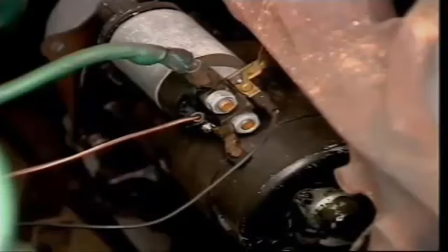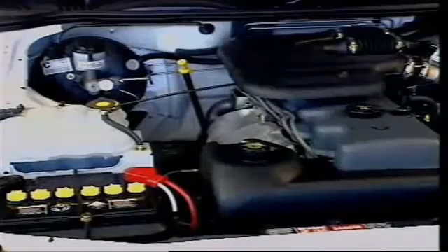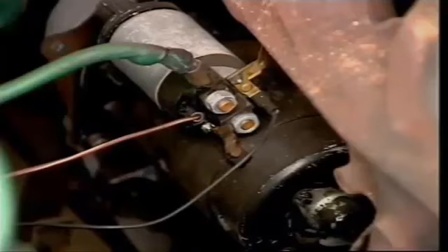The starter motor is an electric motor mounted on the engine block and operated from the battery. It's designed to have high turning effort at low speeds. The starter cables are the thickest on the vehicle, as a high current must be delivered to the starter motor to turn the crankshaft from rest and keep it turning until the engine fires and runs on its own.